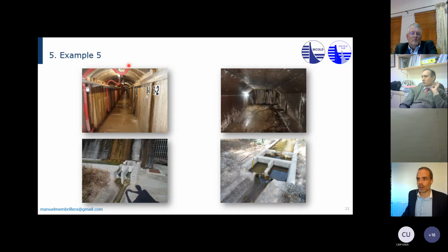So all the dam body drainage is this way. And by the way, this dam has a lot of carbonate deposits. So every 5 years, we re-drill the drainage system in the foundation. It needs to be re-drilled because it's just clogged. It gets clogged because of the limestone and the carbonate deposits.